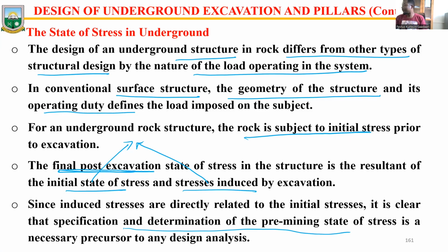So since the induced stresses are going to be directly proportional, it's going to be influenced because before you go in there to do that excavation or whatever, you need to first have a fair idea what your pre-stresses are, which will help you go about your design analysis. And then when you are to do the excavation, you predict that if I open the space this wide, what will be the resulting stresses that will come to add to these pre-stresses that exist.